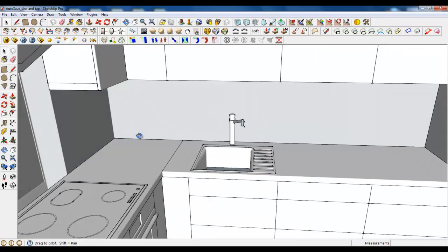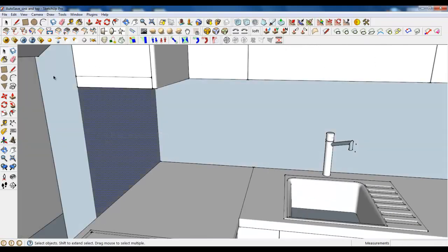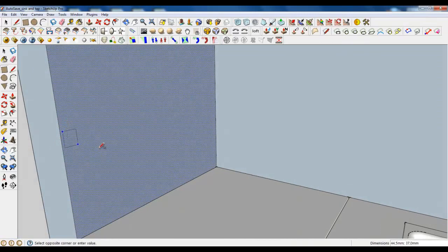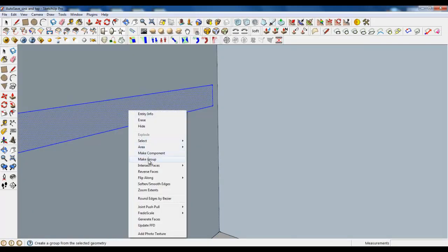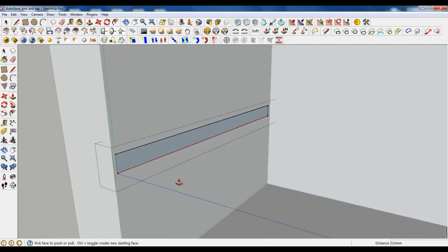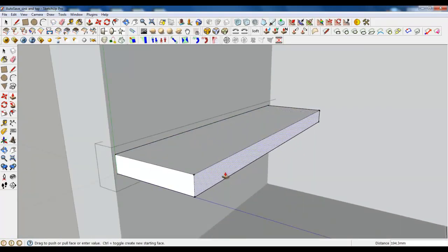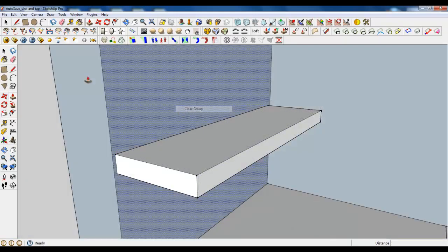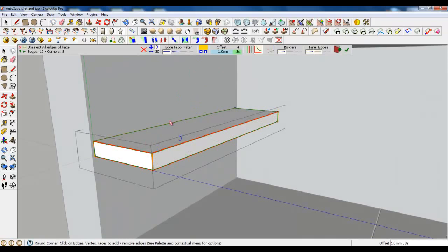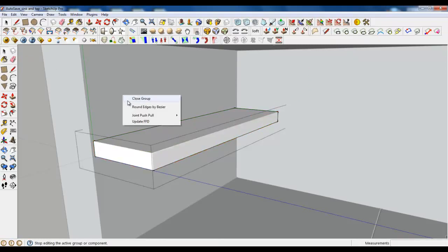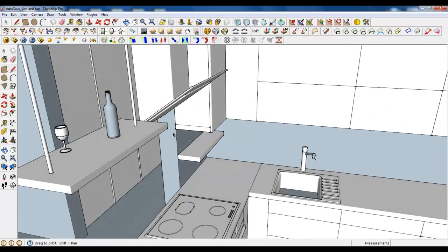Okay, so let's create some shelves. They are simple rectangles, and these rectangles should be rounded with one plugin. We've been using it, so let's follow it for about 200. For boardings, for furniture, I'm using 1 mm and only 3 segments, and it always looks good. In this way you can create another shelf.